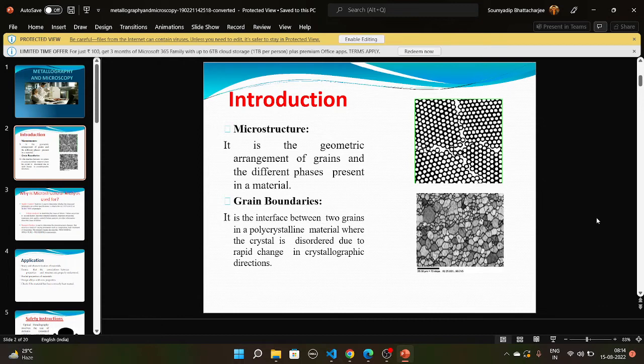So this is an example of materials engineering, that you can design your material as per your requirement. Here the requirement is that our cutting tool should be hard, but it should also be tough. Keeping that in mind, when you can induce some property into it, it becomes a topic of materials engineering. But how can you think of materials engineering if you do not know the structure and property relationship? Now, when it comes to structure, you have heard the terms ferrite, cementite and martensite.